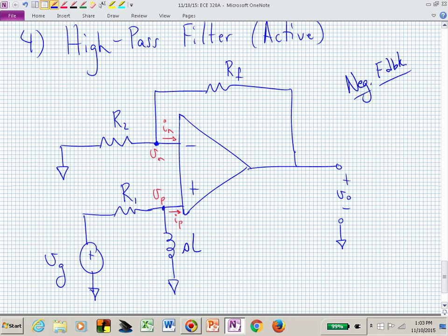So this is going to behave the way that we want, meaning now we know that V sub P and V sub N, the voltage drop across those two is negligible. What else do we know about I sub N and I sub P? Those are going to be zero. This is not absorbing any current or asking for any current into those two input terminals. It's getting everything it needs from the power supply, which we haven't even shown, but it's connected to.